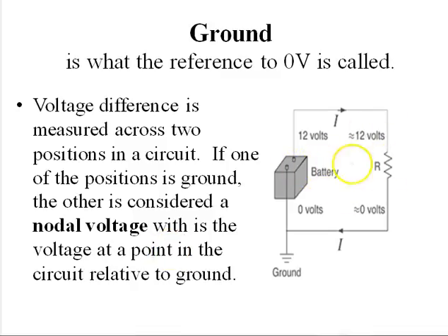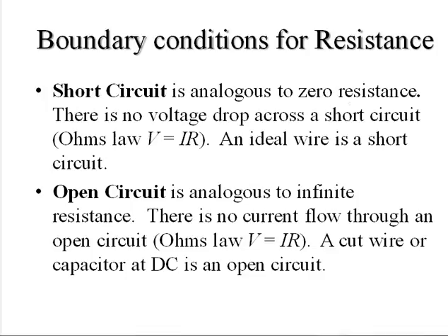So this circuit only has a battery and a resistor in it, but we could take this node up here and label this VB, and we could say that VB is equal to whatever the voltage is of this battery, V battery. We know that that's just at this node relative to this ground voltage here. That will become important for us because it's easier to measure things if we always have one of our voltmeter terminals at the ground. Then we can go through and just measure with one probe. So we'll be measuring nodal voltages in lab.